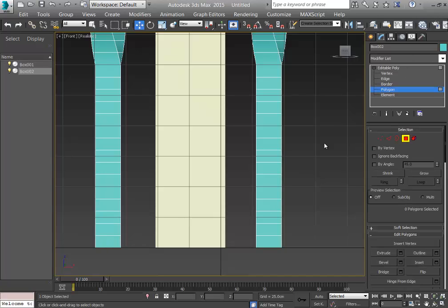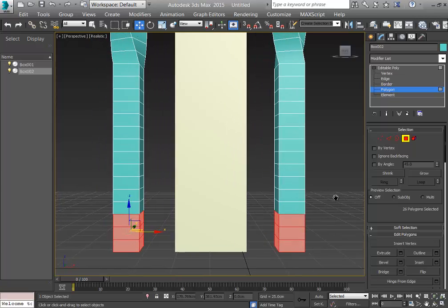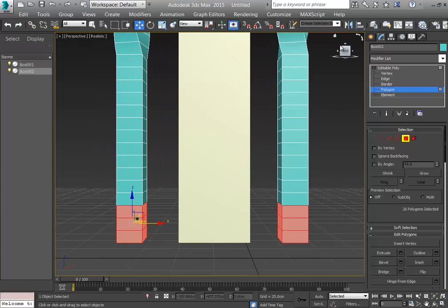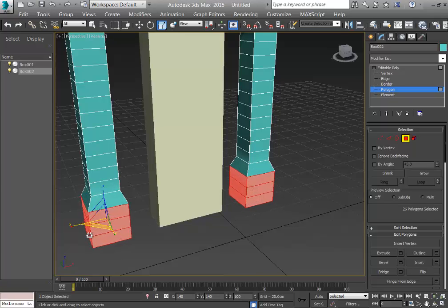What I will do now is select this object. I select the polygon, first 4 are too much, so make it first 3. After I select the first 3, I pass into polygon mode by pressing the letter P on the keyboard, and I select the Select and Transform tool, and I'm going to make it grow on the X and Y axes.